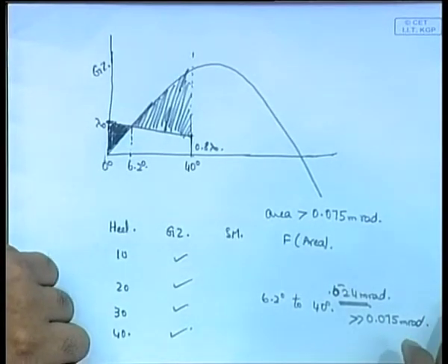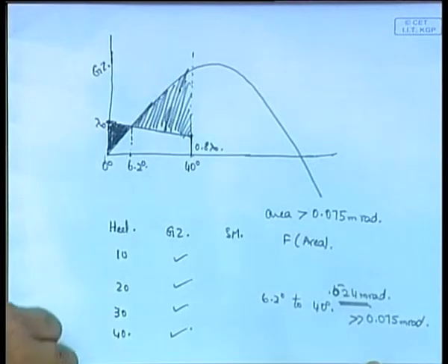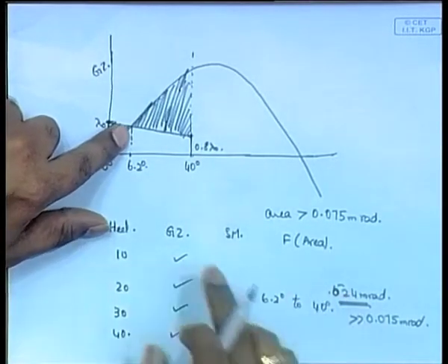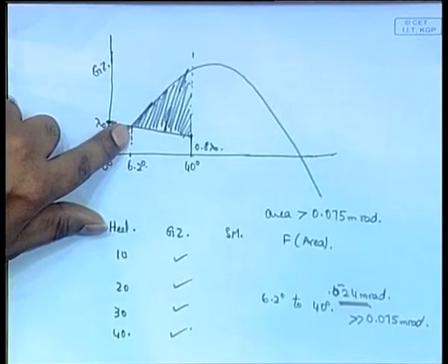Okay. So, I will repeat this because it is very important, and I told this wrongly. First, GM should be greater than or equal to 0.3 meter. So, that is the first condition. Number 2 is the maximum angle of heel. How will you get it? You will get it from the equation for the inclining test.